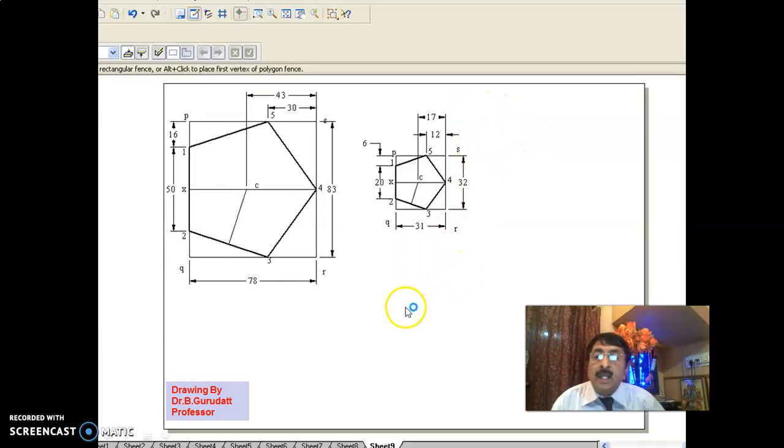Now to do this, as I've done earlier, you go the same way. First you draw the bottom pentagon, a 50 mm bottom pentagon. As you know, it is 50 mm. This is 50 plus 18 degrees, this is 50 minus 18 degrees, this is 50, 50, 50, and take the help of alignment indicators and all that. In that way, write this pentagon first as 1, 2, 3, 4, 5. That is the bottom pentagon.